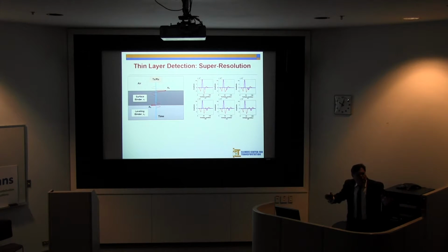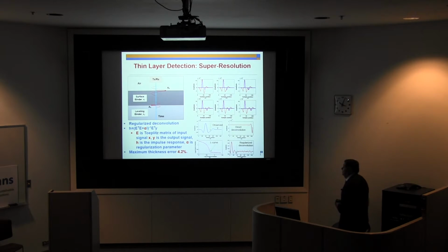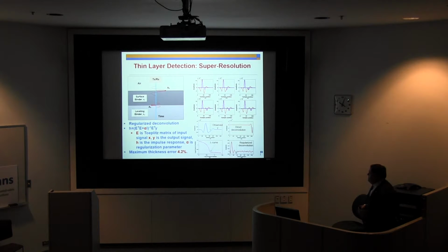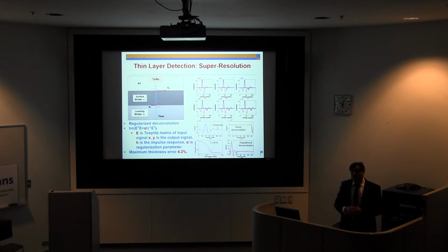At one thickness, you can see everything clearly, but if it is very thin, it needs signal analysis to find it. So we are using the regularized deconvolution approach, and that allows us to measure this even at less than 3/4 of an inch thickness, which is considered very accurate for doing overlays in asphalt concrete.